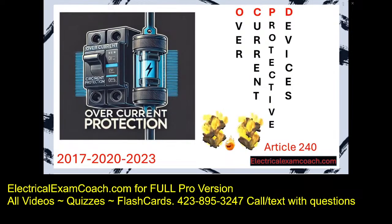I am the Electrical Code Coach from electricalexamcoach.com, and this is lesson 8.3 in our video series. We're still in Article 240, but we're going to be doing sample calculations of whole homes and businesses and selecting the main overcurrent device. Learning how to take all the work that we've done in the program up until this point, the load calculations and everything, and then take those total VAs and find out how to choose that overcurrent device, which will ultimately dictate the size of the service.